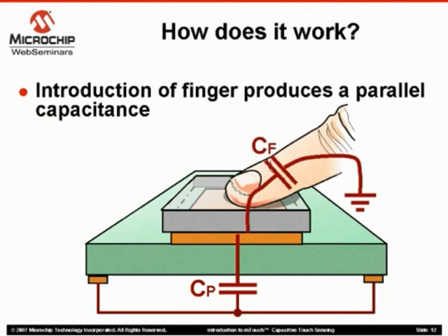A finger touch will add a second capacitance in parallel with the pad's capacitance. The iron in an individual's blood creates strings of capacitors between every surface of their body. So, when someone creates a capacitance by moving his or her hand into close proximity of another conductor, it creates a capacitance essentially coupled to ground.